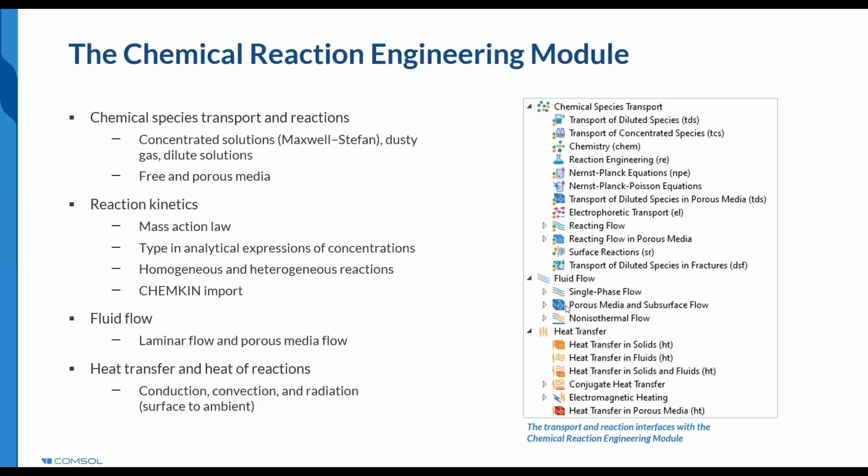Finally, we also have the reaction engineering interface here, and this provides a means to define the reactions and compute the behavior for idealized reactor models, such as a perfectly mixed batch reactor or a plug flow reactor. And this can help you examine the kinetic behavior of systems under ideal conditions. The reaction engineering interface itself is a zero-dimensional physics interface, and is used to help compute the mass and energy balance equations for describing an ideal